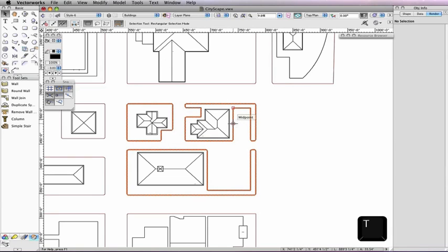You will see a small box around the snapping point to delineate that a smart point has been acquired. Vectorworks can remember up to 3 smart points, and then as new points are acquired, the oldest points are replaced.